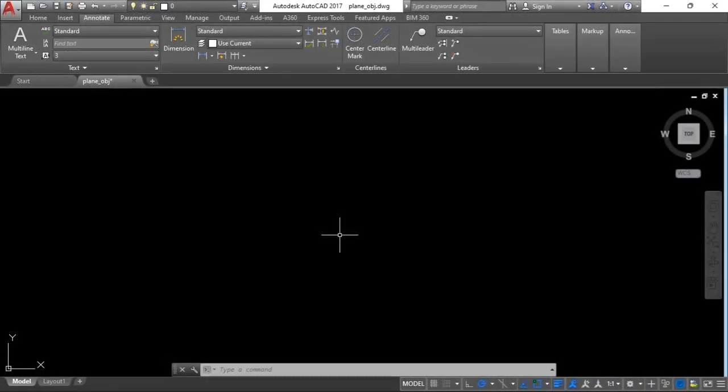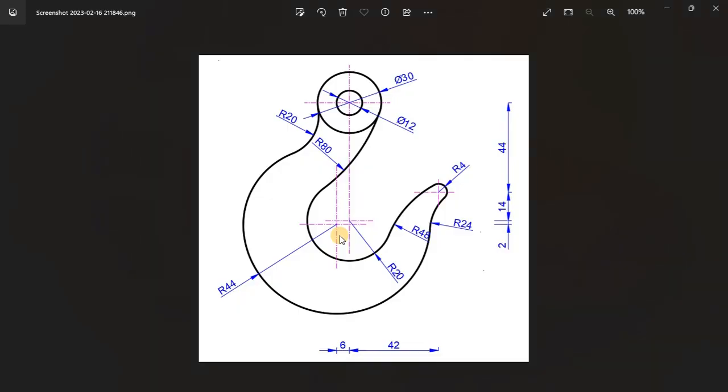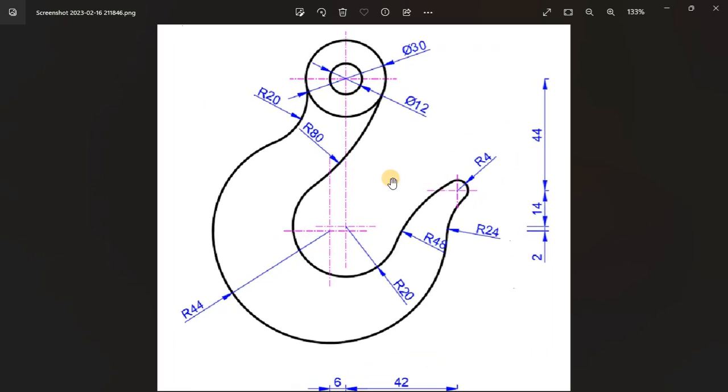Before attempting that drawing, the first thing you need to take care of is to mark the position of the centers. In any of such complicated drawings, you have to always look at the circular parts or parts that have curves and take care of their centers before you go on to do anything else. I think that is the easiest way to go. On our drawing, we're going to look for the centers. We have a center right here, and centers here, here, and here. So we make sure we mark those centers.